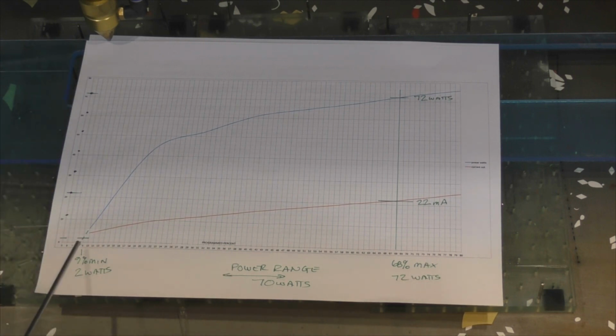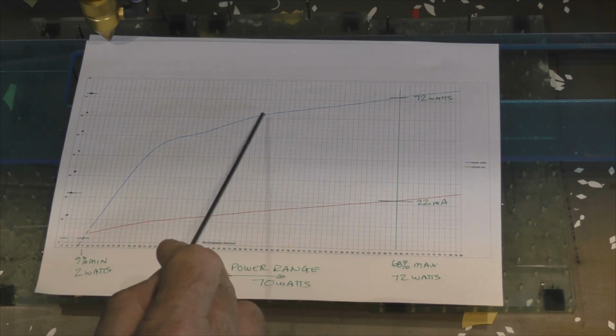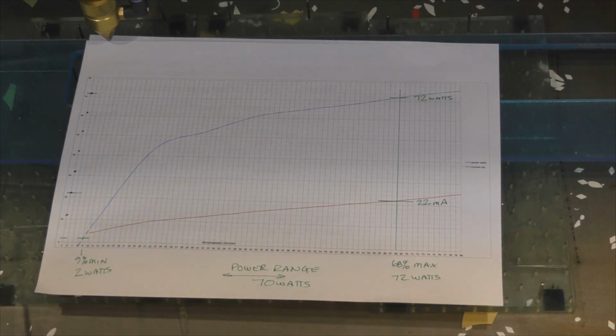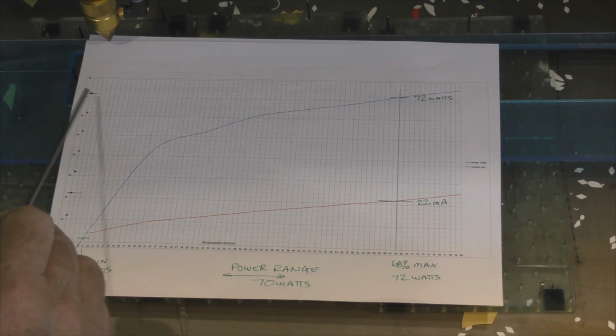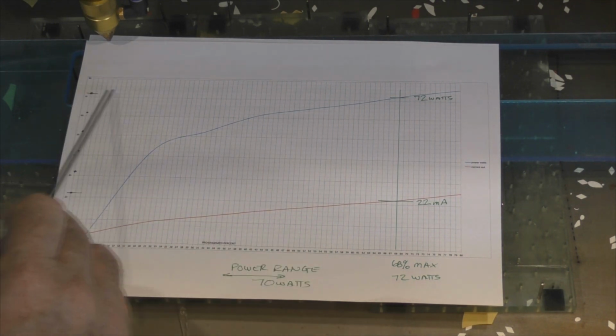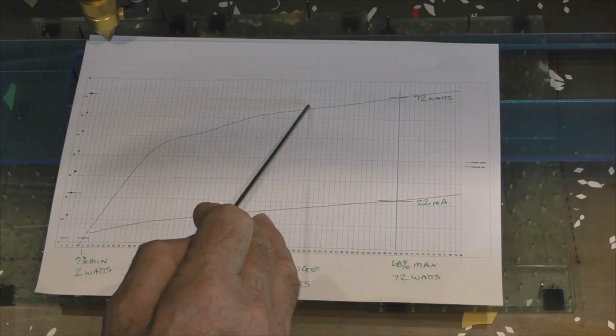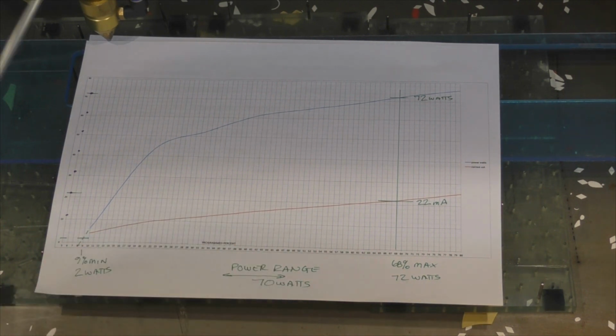And as you can see, if I select 50% power, I'm not getting 50% power because it's a totally non-linear relationship. So this is a 70 watt tube and it's up here at 72 watts at its limit. But so therefore you'd expect at 50% maybe, if you've got this misapprehension, that I would get 35 watts at 50%. Well, at 50%, I'm getting something like about 66 watts. That one is blown out the water.